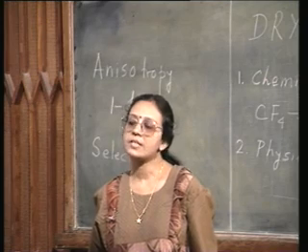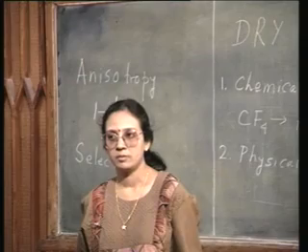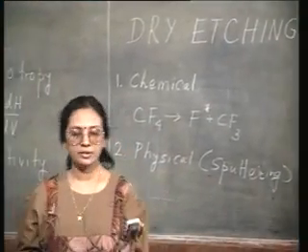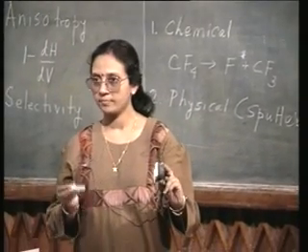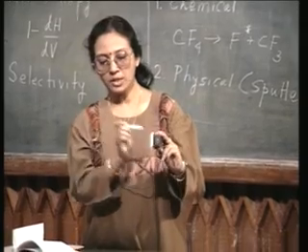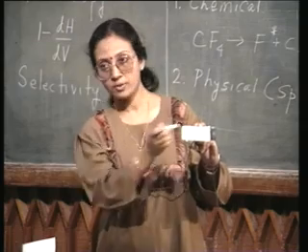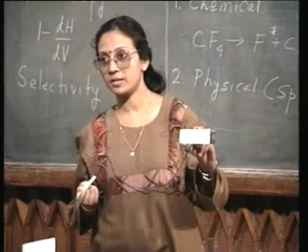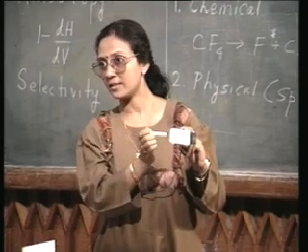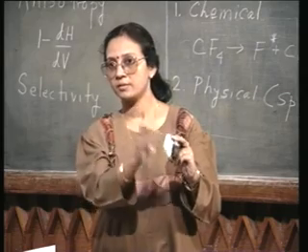But it is possible to realize very good anisotropy, because you see, suppose this is my substrate surface, ions are getting impinged like this. So, only on the surface on which it is getting impinged, you can see the surface particles getting dislodged, right. Only on that surface etching is taking place. What about the sides?